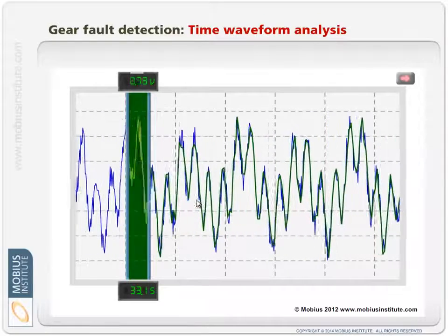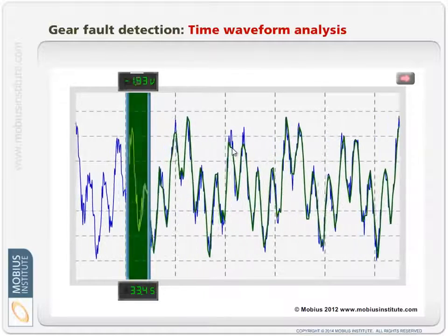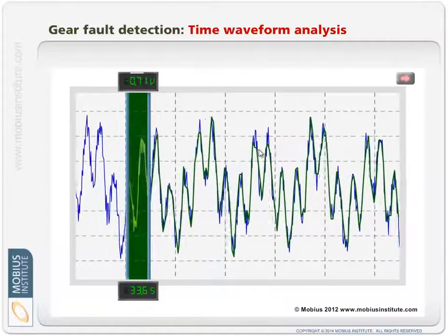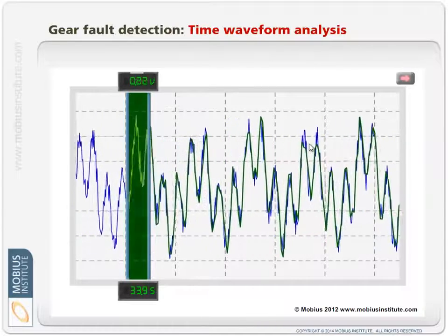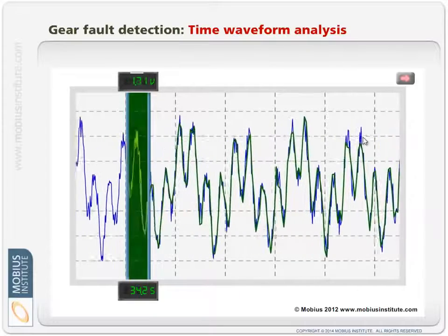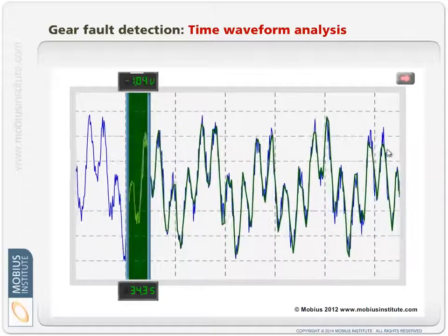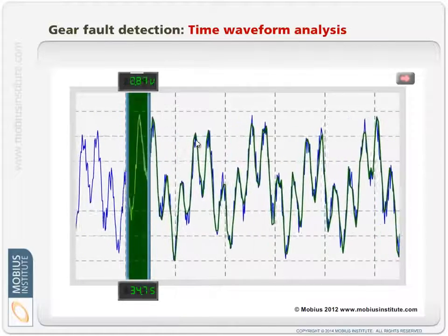I can't illustrate that easily, but if you look here, you'll see there's a blue spike that goes up, but we didn't capture that. The green captured waveform is lower. We ideally wanted to get a digital sample up top here. You can see it there as well. We didn't capture these spikes. We sampled, even now we're sampling too slowly. We might just fluke it.